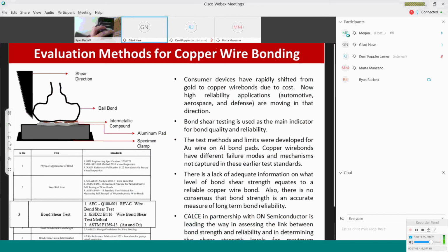And so we work at all those different levels. For example, one area, if you just start really close to the die, you can start with copper wire bonds. Traditionally, people have wire bonded with gold for high reliability. Gold became very expensive, so people wanted to see if maybe they could wire bond with copper. After all, you have copper wire in your house. Why couldn't you have copper wire in your electronic components?